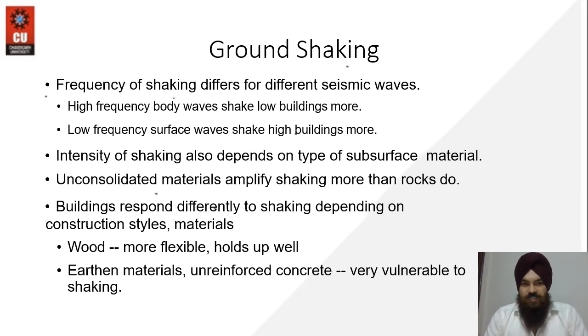First is the frequency of shaking, which differs for different seismic waves. High frequency body waves shake low buildings more. Low buildings means low-rise buildings, single-story or double-story buildings. Low frequency surface waves shake high buildings more. That means high-rise buildings of more than 3, 4, or 5 stories. So they are more vulnerable to damage if the frequency of